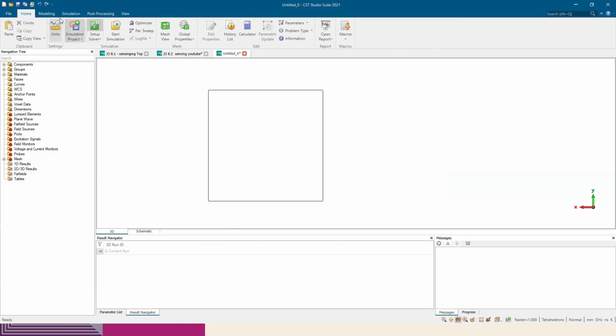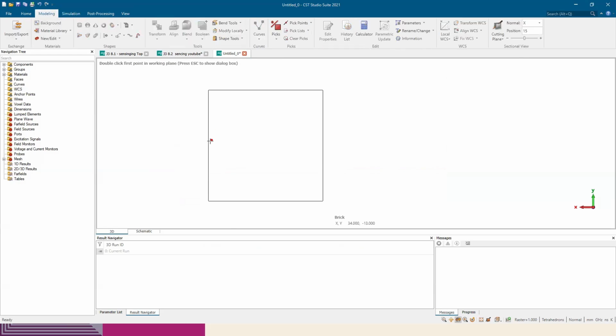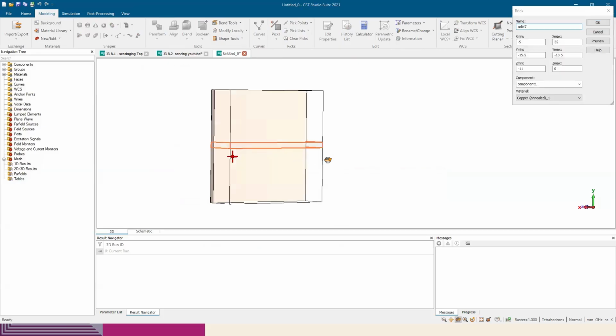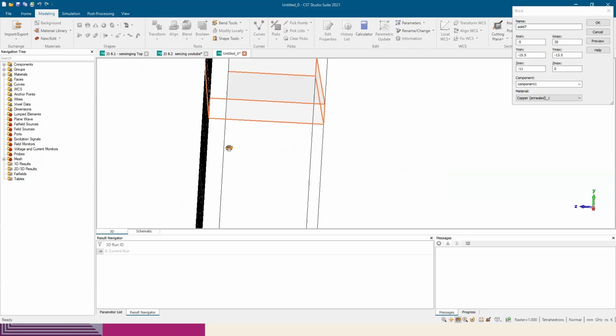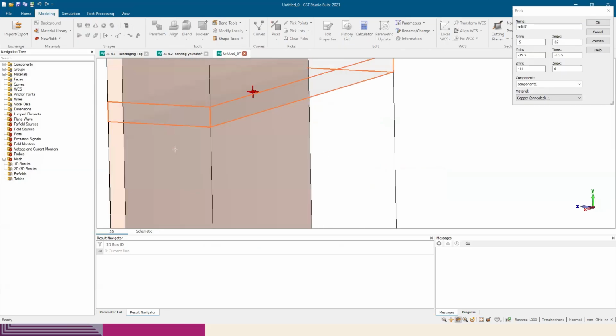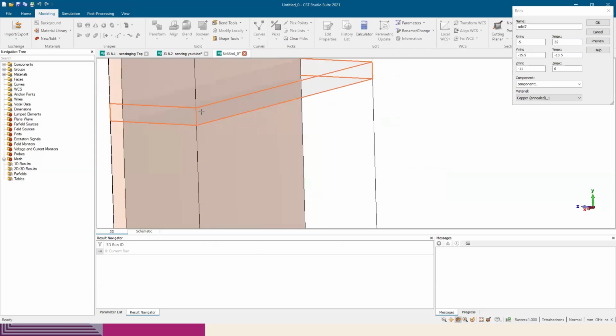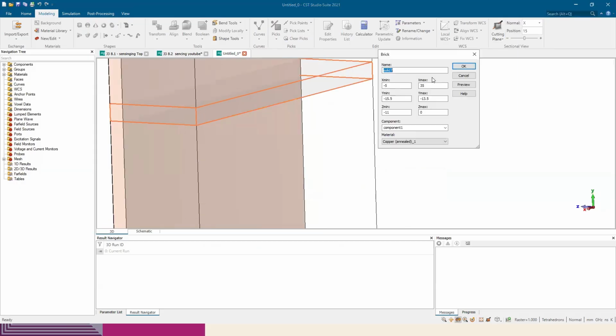I forgot for now, so let's make it by ourselves. Remember, I'm just showing you. You need to calculate the length and width of the transmission line in CST by yourself, because your simulation may be different, your substrate size may be different.